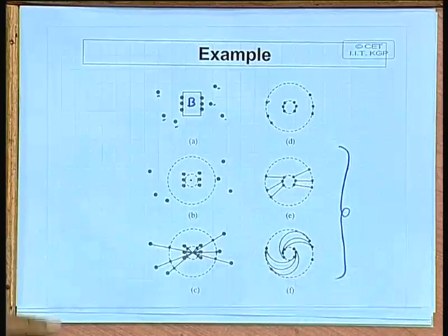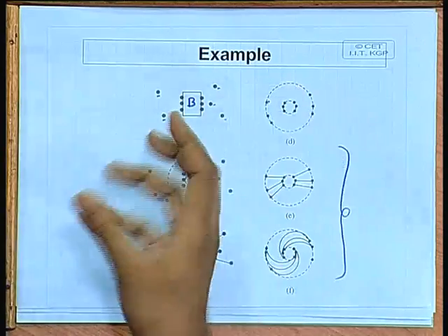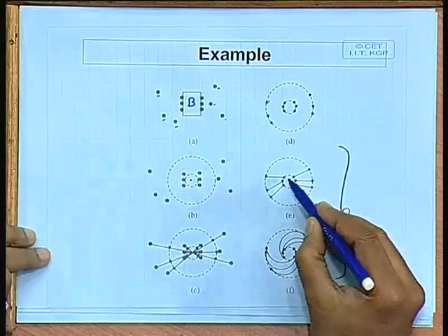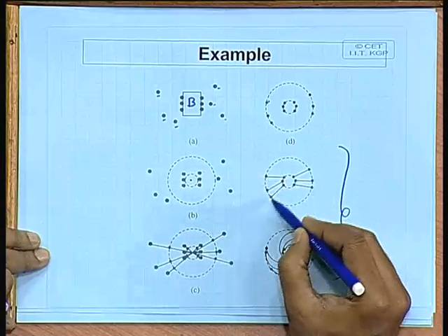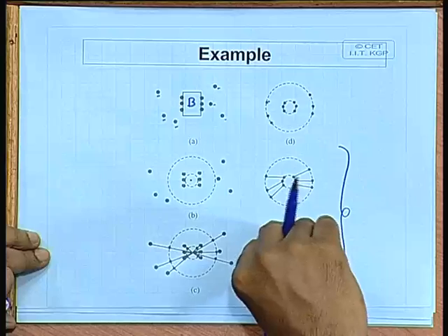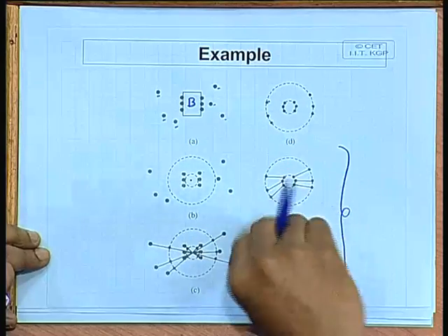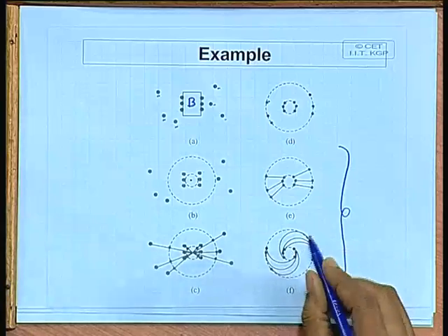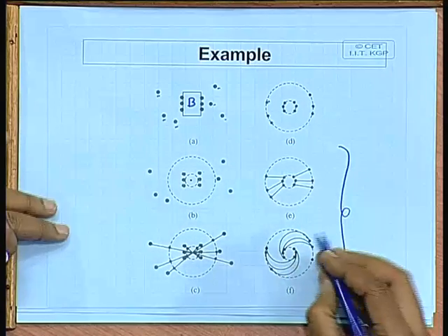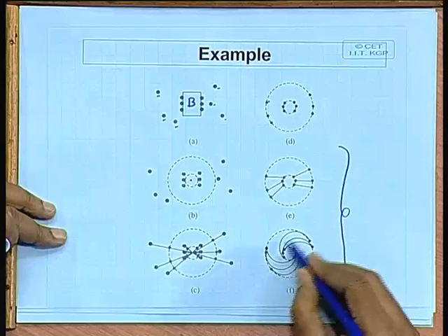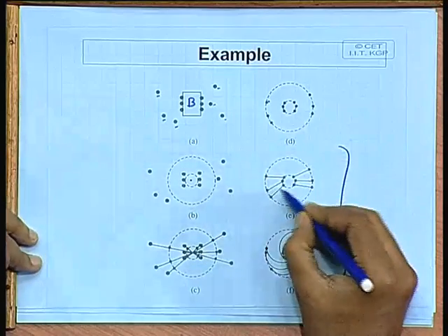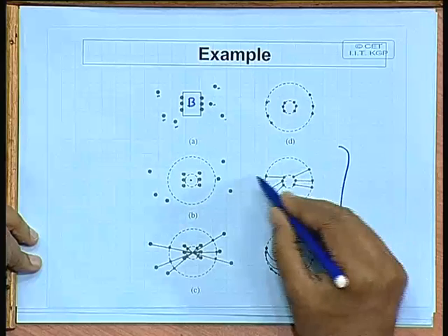Now, what do they try to do? They try to rotate the inner circle. This is the worst case scenario, this is the best case scenario. Suppose this is the order in which you want to connect the lines, but if you rotate the inner block, then the interconnection will become a little skewed. So, this method has an estimate to find out the length of the nets if you rotate, that is, what orientation of the block will give you the best interconnection solution.